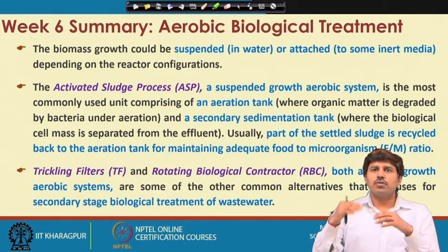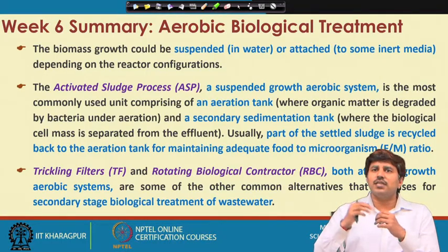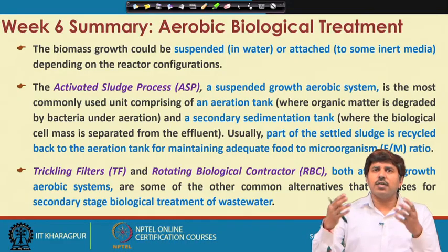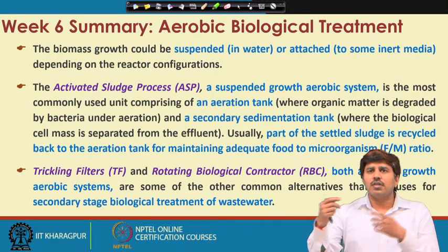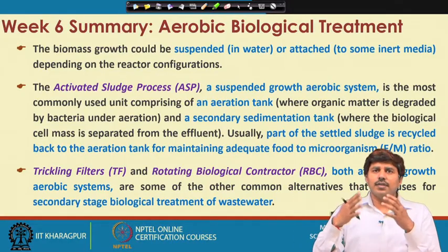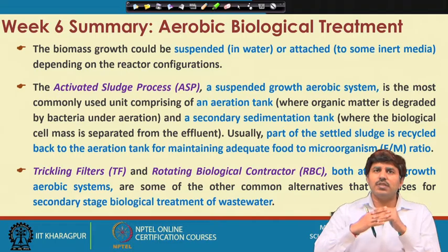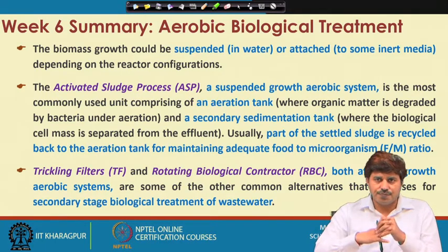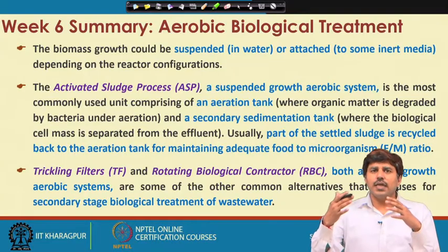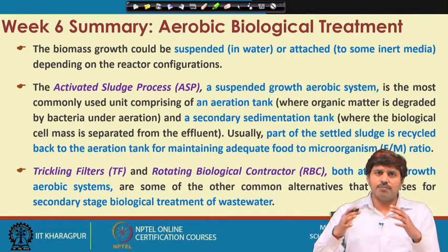Okay. So, the retention is better in the attached growth system, because once they are attached to a media, they do not easily get washed out, whereas in the suspended system when the water is taken out, the microorganisms suspended in that will also come with it. So, the biomass retention is poor in the suspended systems as opposed to the attached growth systems.